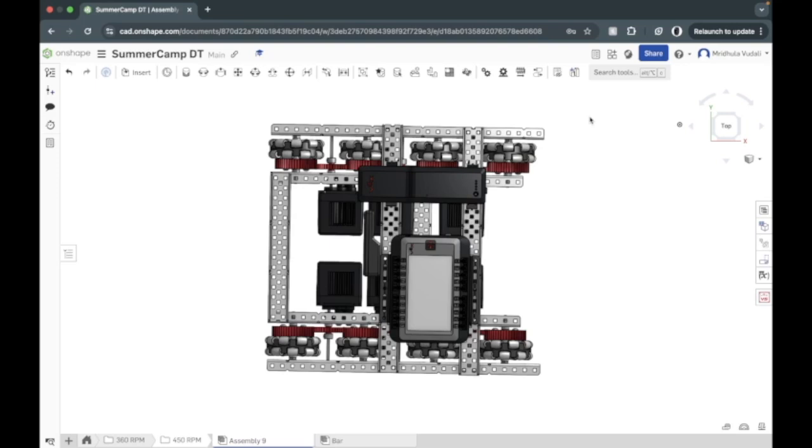Also, keep your battery cable length in mind. It's always better to position the battery as close to the brain as possible so that your battery cable has a lower chance of being dislodged from the brain. Lastly, for the radio, since all we currently have is a drivetrain, you have a bit more freedom for where to position it. The same rules as before apply. Keep the radio safe and in a position where the wire can reach the brain without risk of disconnection.